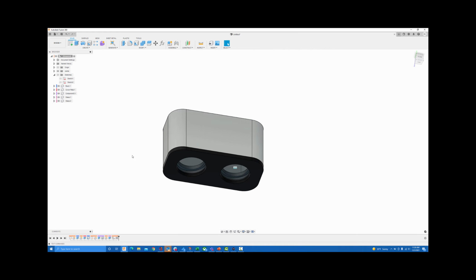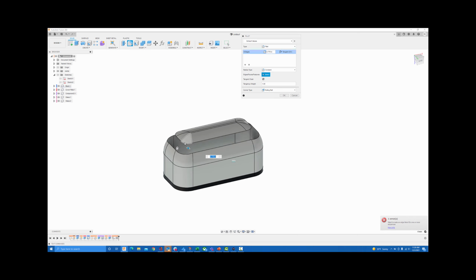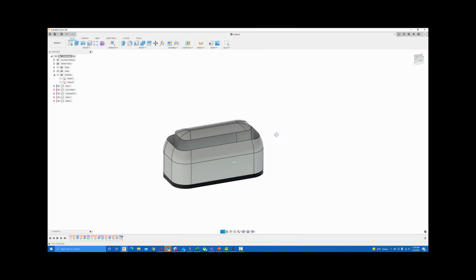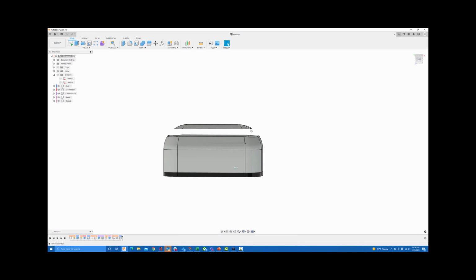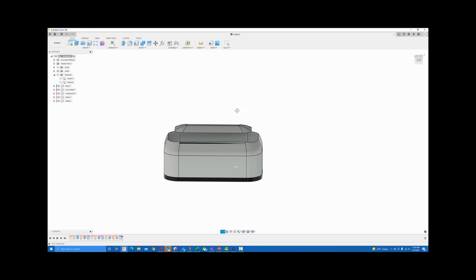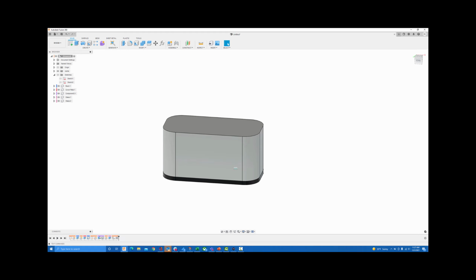What you will find is you probably want any of those fillets before the shell. And the reason for that, if I grab that and start dragging that, you'll notice that you get a gap there. And what's happening, I'll hit OK, is it shelled it and then it filleted it, and it's not keeping a constant wall thickness across the inner edge as well. So I'm going to delete that. I'm going to roll my end of part marker all the way back before the shell.